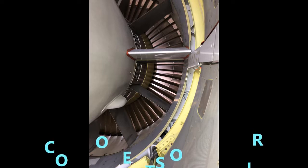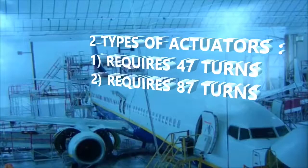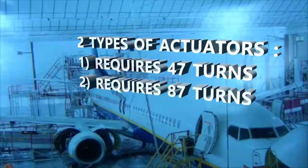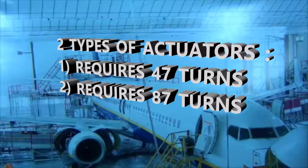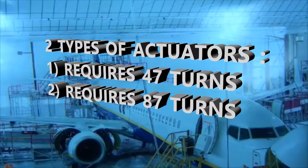You have also two different actuators. I did want to mention that because there's a lot of different things, but I'm just giving you the main components, and I just wanted to mention the actuators. There are two different actuators that you can install. Please pay attention to part numbers on the tags, because there's a lot of things that look alike, and you think, oh gee, that goes there, and you didn't pay attention to the part number that was required from the aircraft maintenance manual.